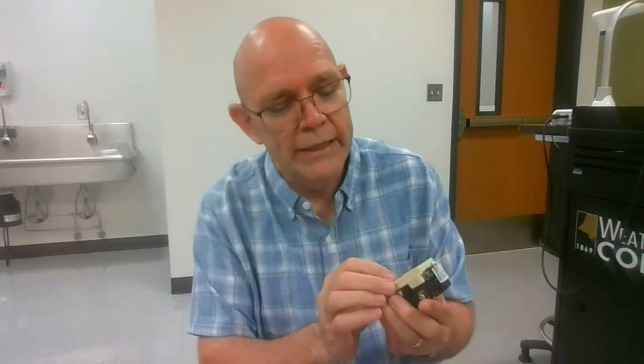All right, it monitors how much leaves and how much comes back. If there's a short and someone's leaking out into a puddle of water or something, there's not as much coming back, and it will flip it off, and you'll have to go in and hit the reset button. When you hit the reset button, it'll pop, and then it will let electricity go through again. But if you haven't fixed the problem, it's going to pop right back off. So once again, you have to fix the problem.